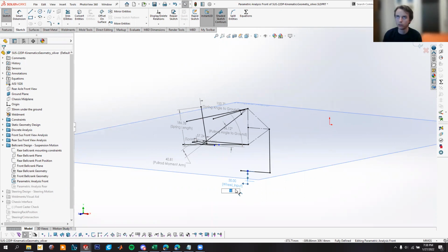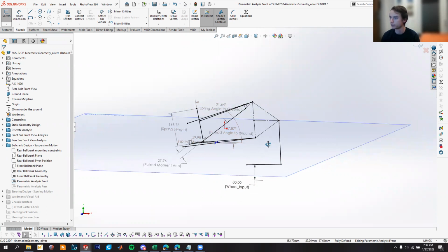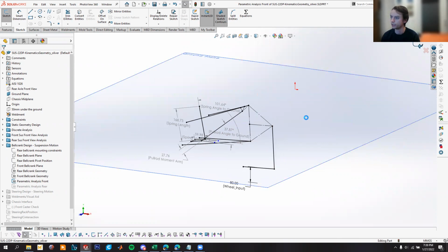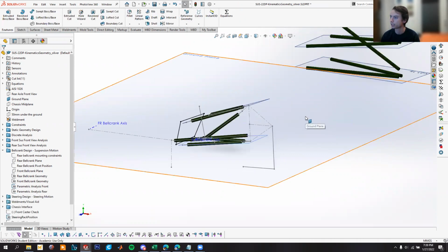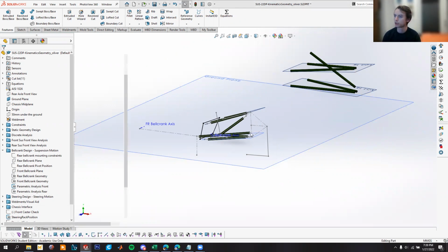The required amount is 25 millimeters by the FSAE requirements, and so we have slightly more than that in our designed wheel travel. So to put it up to a maximum condition, you can see that the linkages update, and this is now in its bump position. So I exit that sketch, and we go back over to the assembly.